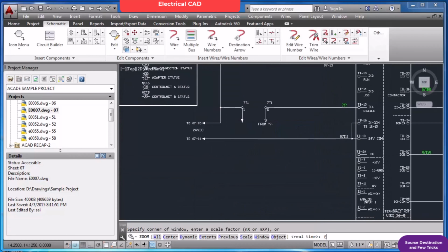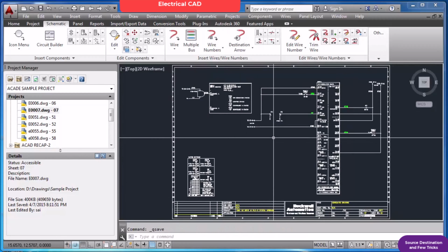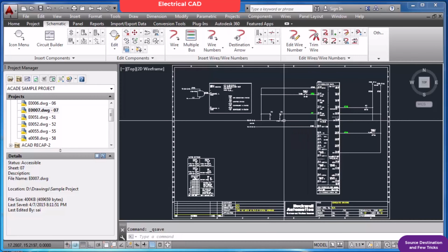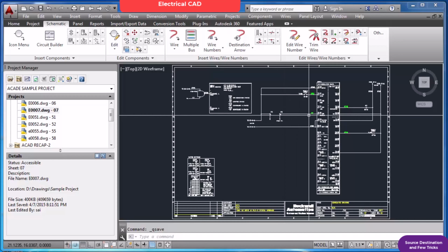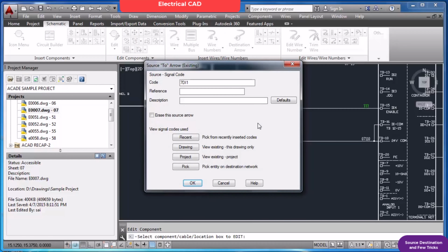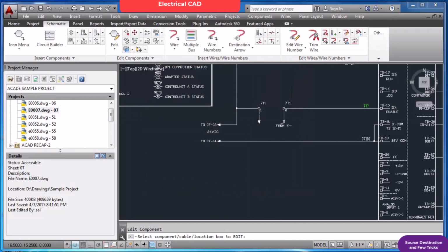Okay. So while making the first drawing, I will put this, then I will save as, and if I have 50 drawings, 50 such drives, I will save as, and I will change the tag. So this tag will change: now at present this is 7, when I save it into 12 and update the tag, it will automatically become 12. 7 will become 12.